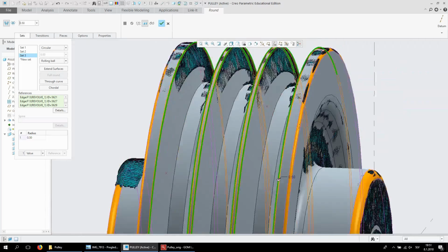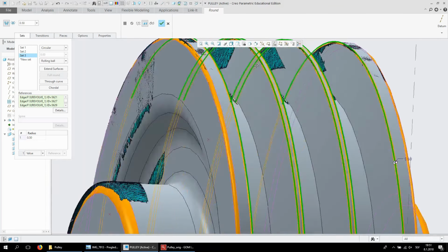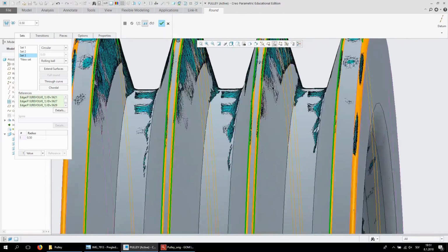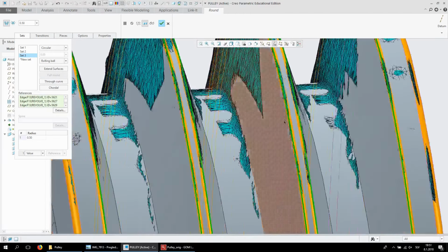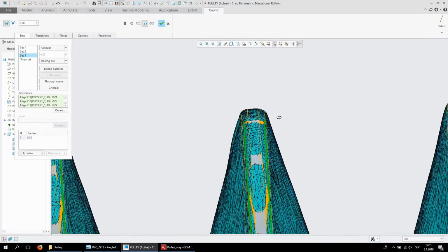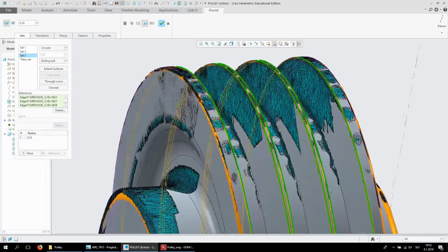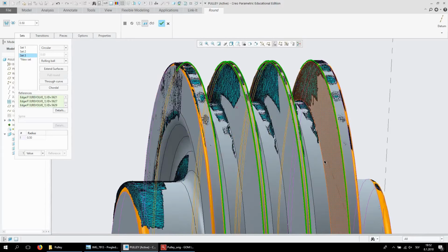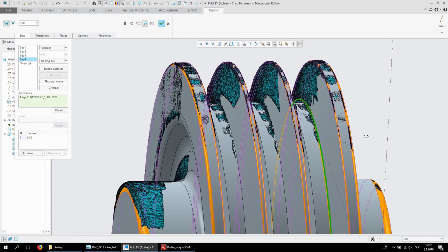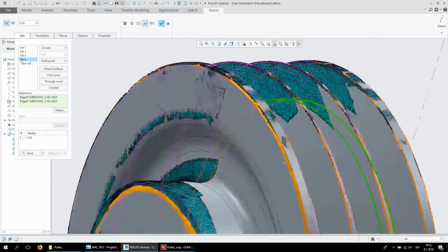How does that look? Yeah, that looks quite okay, I think, because there shouldn't be too much of a round. Yeah, this looks good. And the insides also. So again, you don't hold anything, just click, and now hold Control and select the rest of the edges.